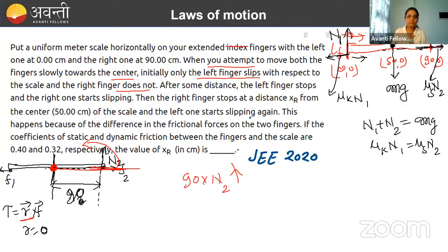Done. Because of friction, it is what? 0. Because here R is 0. This force is intersecting this point around which we are calculating torque. So that is 0. F1 also 0. Now this is your N1. Now the torque distance is how much? This. So R cross F. How do I do R cross F? I start from here, R cross, going toward N1. N1 is in upward direction. So this. So this is in which direction? Initially this force was at what distance? 50. So 50 into N1 I will write in this direction. Done. So these two are in opposite directions.